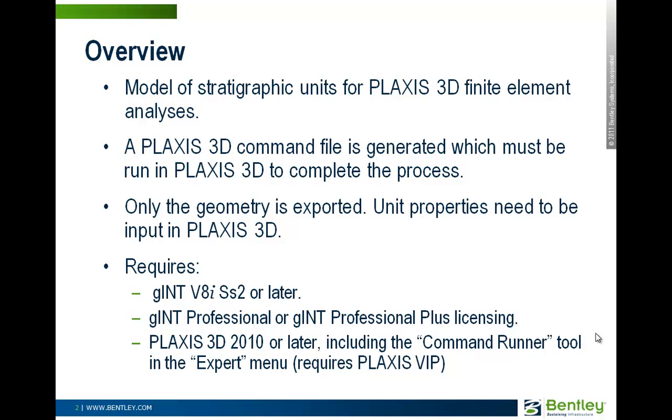This capability requires gINT V8i SS2 or later, and you must be licensed for gINT Professional or gINT Professional Plus. And it also requires PLAXIS 3D 2010 or later, including the command runner tool and the expert menu, which requires the PLAXIS VIP licensing.